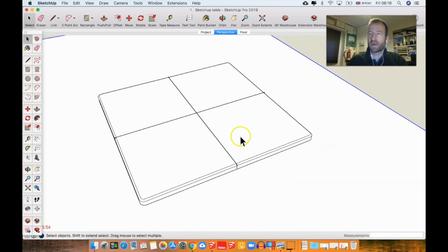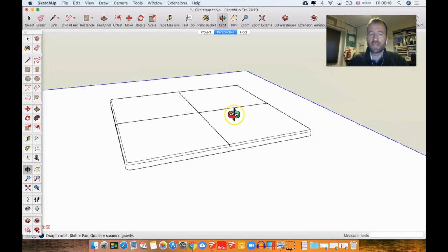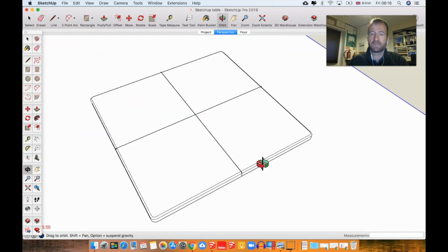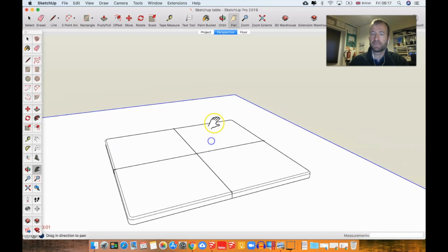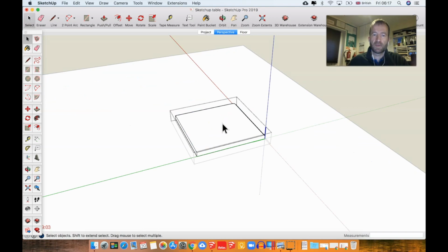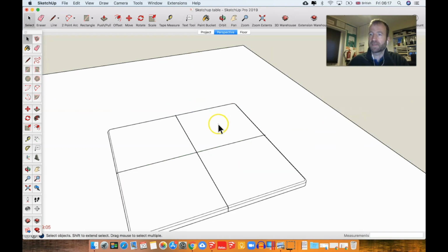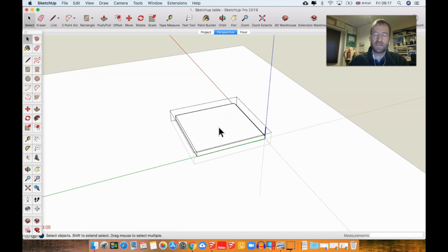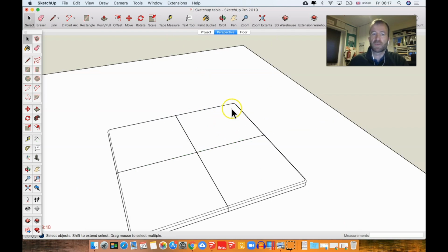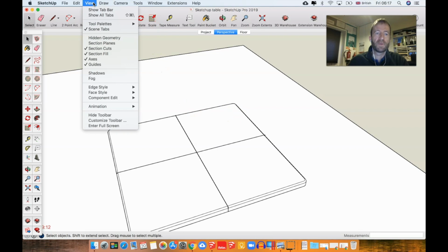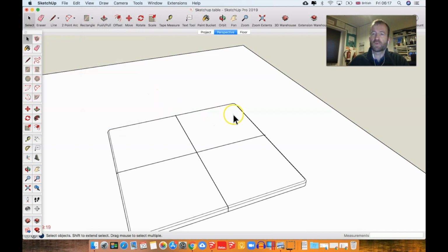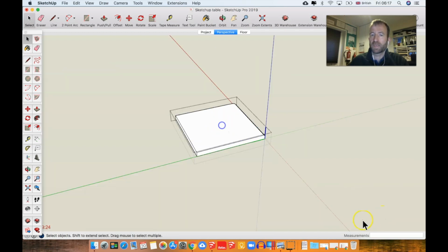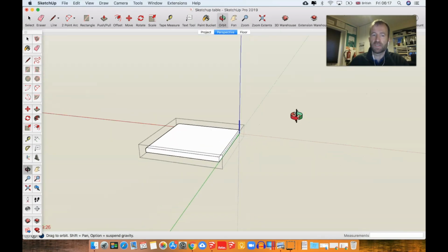Now you remember I talked about hiding lines, hiding geometry with the eraser tool. There's a few bits we need to hide here. I could have done that earlier, but you can do it later by making sure that you are isolating the other geometry. So I've got a setting on here, up at View, Component Edit, and I've got a tick next to Hide Similar Components. You can also tick Hide Rest of Model, and that means that when you're editing a given component, which you can do by double-clicking it, you isolate that visually.